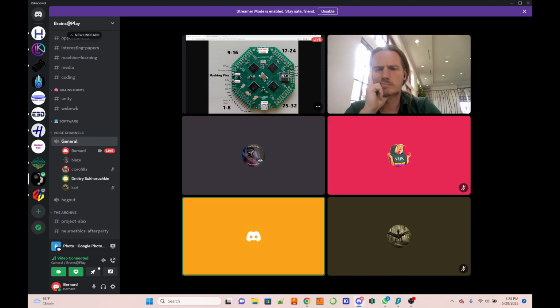So for this inside power, it's better to only check it, because if you have some problem with this power, then you can destroy the board. Because 5 volts also can destroy something. With 3 volts, you can accidentally provide some 12 volts, as I always do. If you have 9 volts, it will destroy the board. But with the isolator, you will just destroy the isolator, or not destroy it. It has more protection.